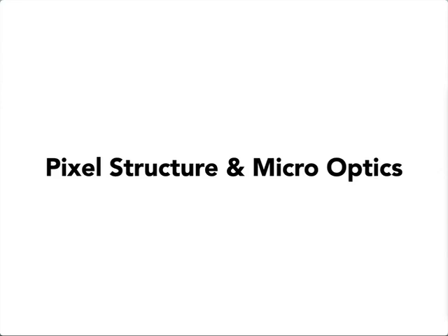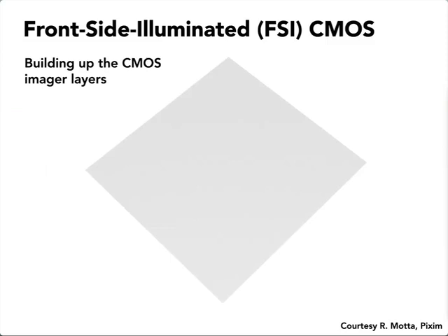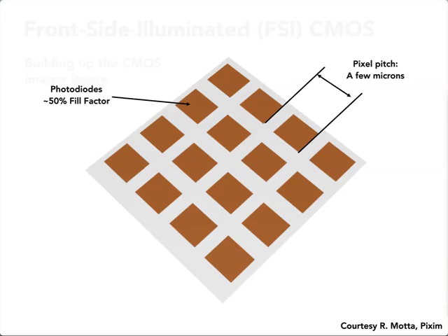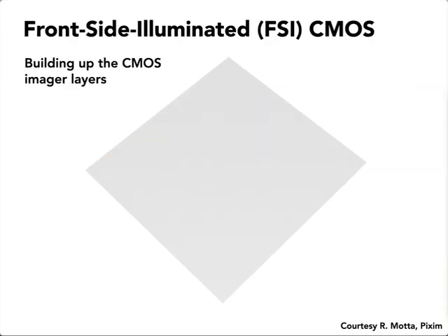Okay, so first, let me give you a bird's eye view of what the sensor looks like as it's laid out. I'm going to show you how this builds up in the layers of the sensor surface as it's being fabricated, as a cartoon, to give you a sense of the typical layers and processing elements that are present in a typical CMOS sensor. So we're going to do a patch of sensor that has 4x4 pixels.